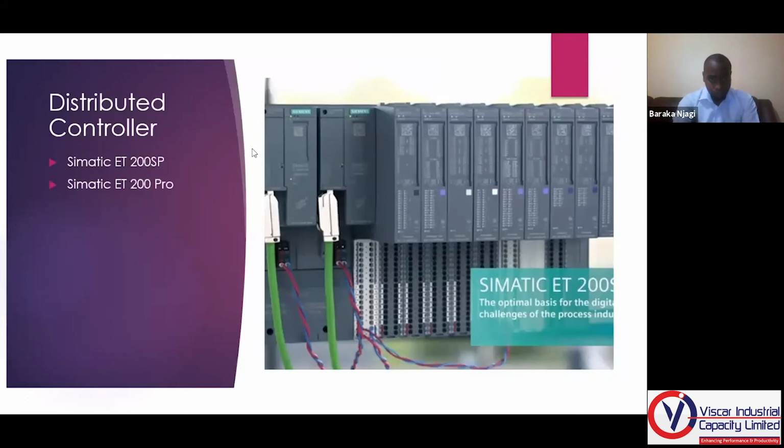Then we have what we call a distributed controller, as you can see on your screen right there. So imagine you have your basic PLC at point A, but you have your actuators and your sensors many kilometers away. For example, in an oil industry, you have sensors that are thousands of kilometers down, but your basic controller is near the ground. So how do you program it so that those sensors can communicate to the PLC? It might not be logical to have sensor cables connecting from down all the way up. So what they use is called a distributed controller.